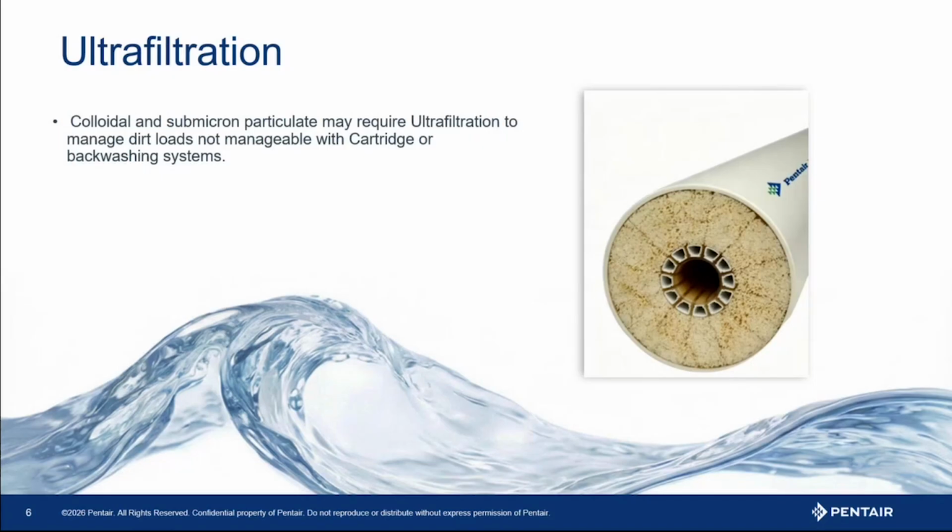Some well strata may be in clays where that clay is super fine and sticky, and you need something that can wash itself to survive in that environment and not create nuisance fouling and those sorts of issues. And sometimes debris, even super fine sand, may come out of a well where you may need something like ultrafiltration to handle that. So please be aware that those options are out there.